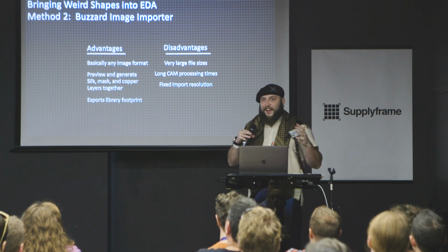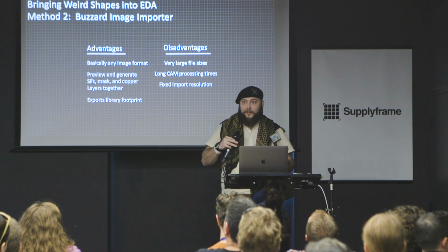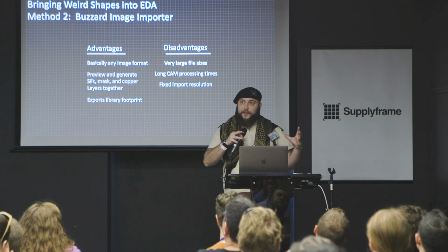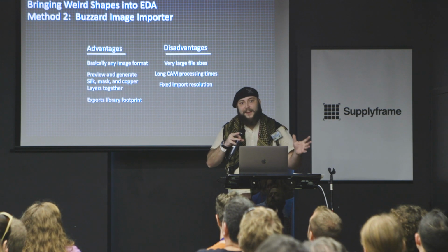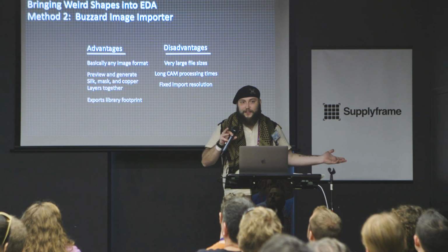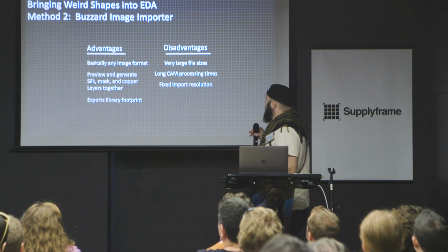And they're all grouped together, but when the CAM processor goes to actually make those into Gerbers, a CAM job that might normally take like 30 seconds can take upwards of 5 minutes. But you're doing that once over the life of a board, hopefully. So, you know, it's not the end of the world.